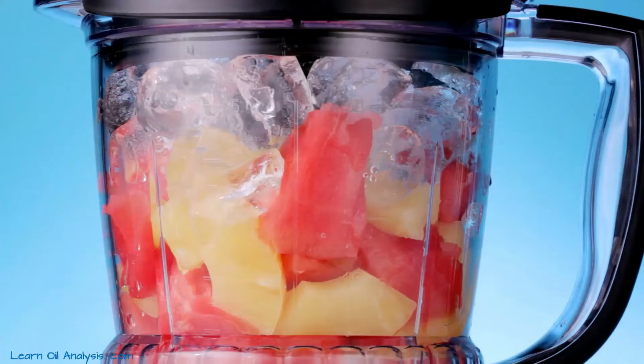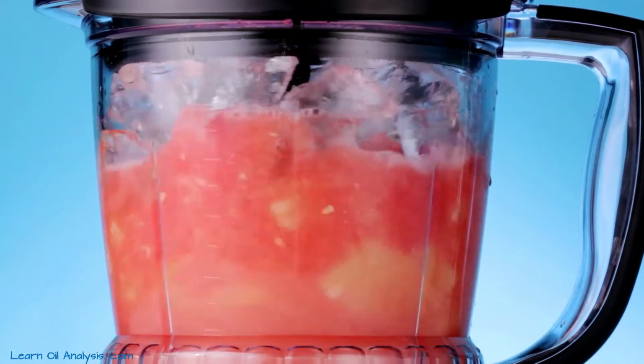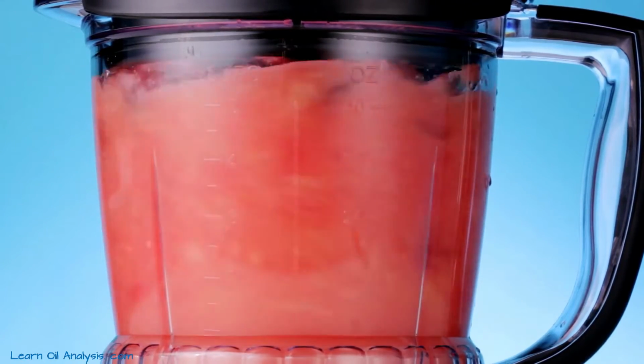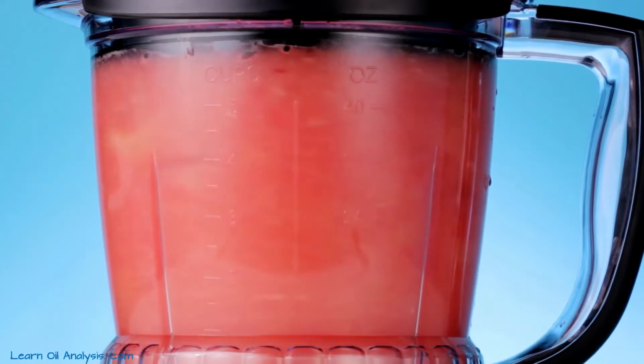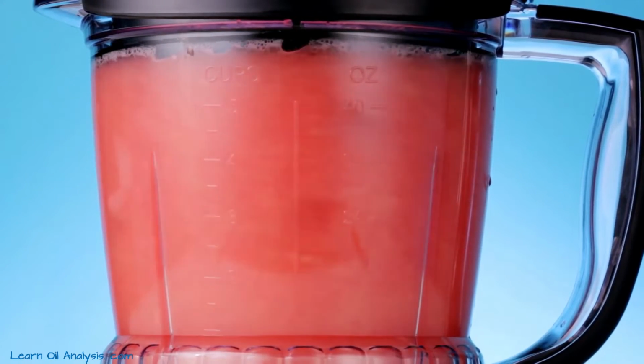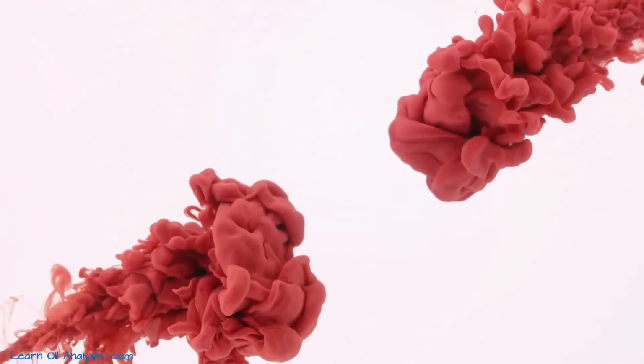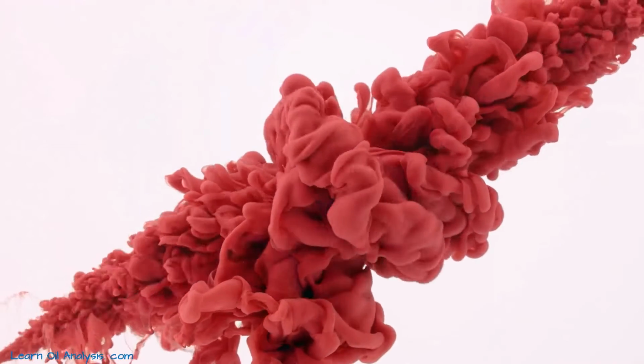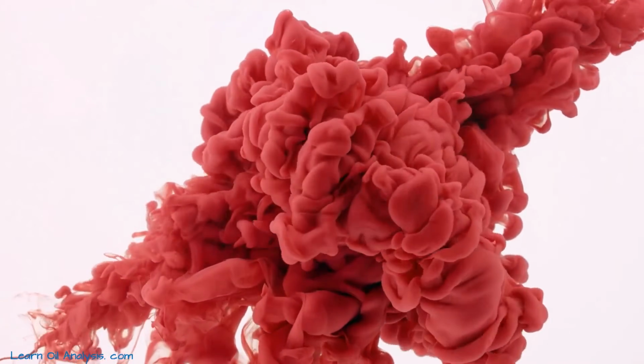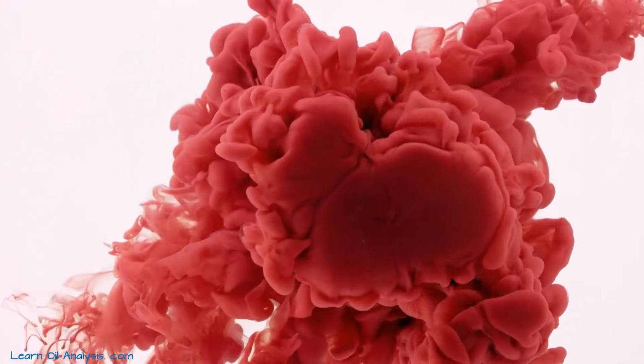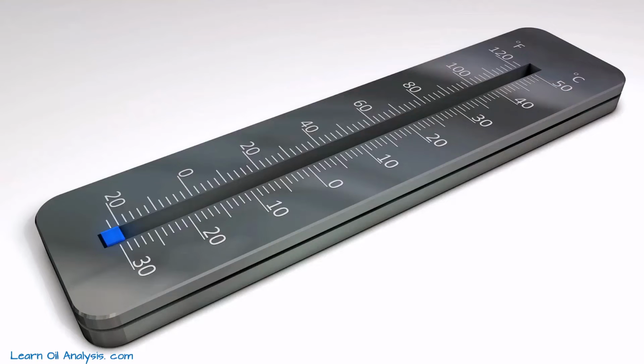Now consider arcing. This is a more severe form of electrical discharge. Replace the electrical scissors analogy with a blender. Rather than a few gentle cuts here and there, it smashes all the oil molecules in its way to get from one electrical contact to another, and reforms into complex hydrocarbons. Here, the high temperatures cause the oil to decompose, leading to the creation of hydrogen and especially acetylene.